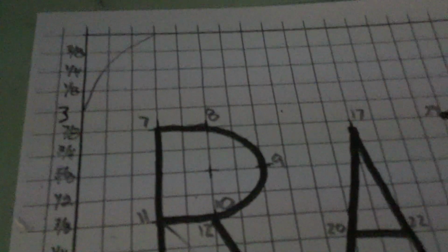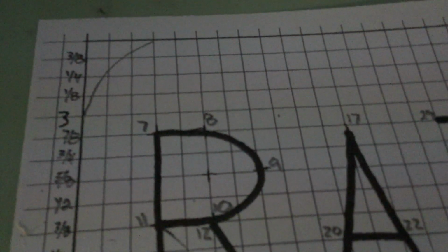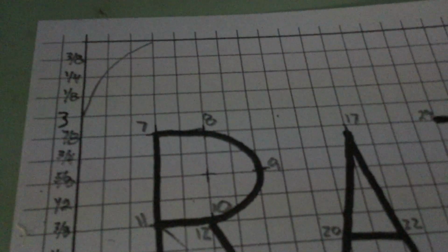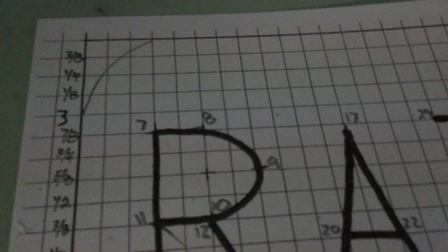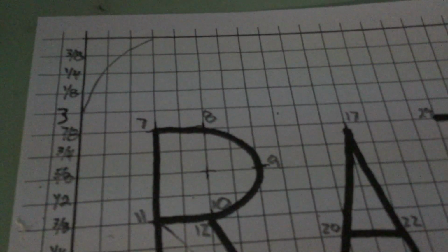Step 8, we come over. Now, this is where it gets tricky and it took me a little bit. Step 9. It's having you cut a what? Is that a straight line? No. Clockwise. Okay, it's an arc. So the thing about the arc is you put G02.